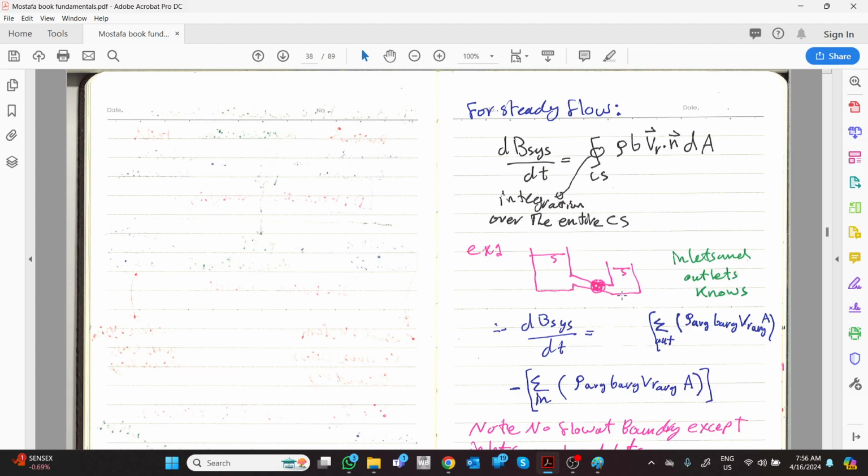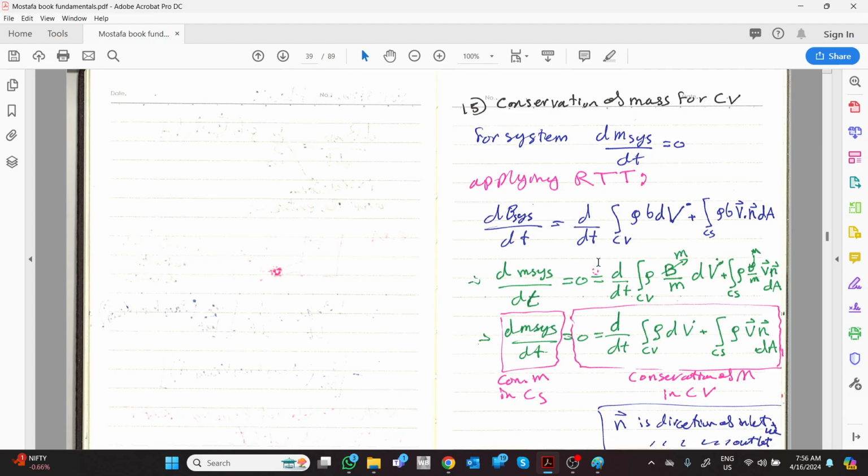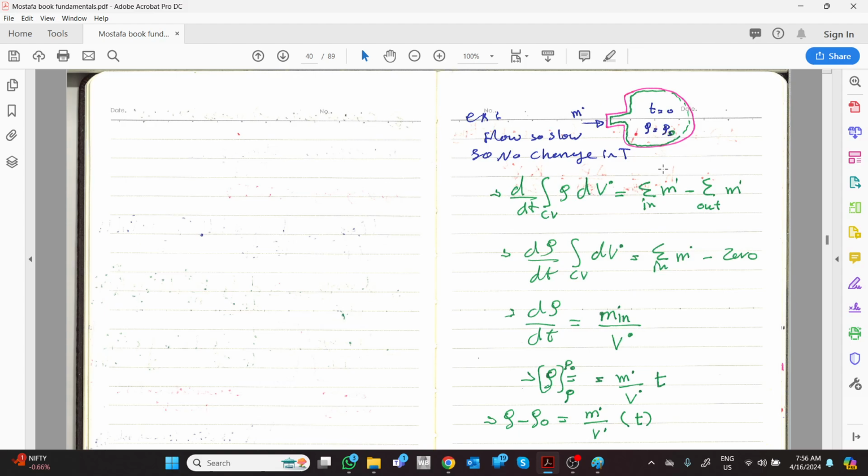And if you're trying to apply the control system to, for example, a pipe, a sink and a big tank, what is your control system? You have a lot of surfaces, and these surfaces are not a boundary, not a wall, so you need to calculate in and out on each surface, which is not defined. So it is the wrong direction to follow a control surface. When you have confined areas like a water tank filling and pipes, use Reynolds transport theory.